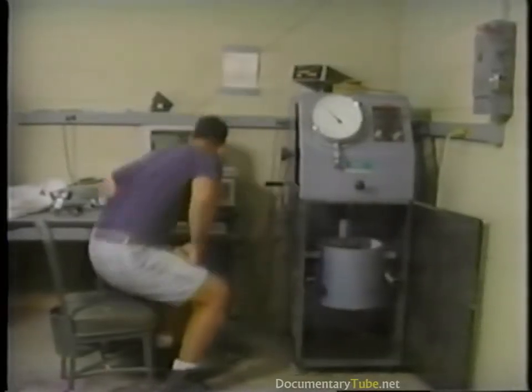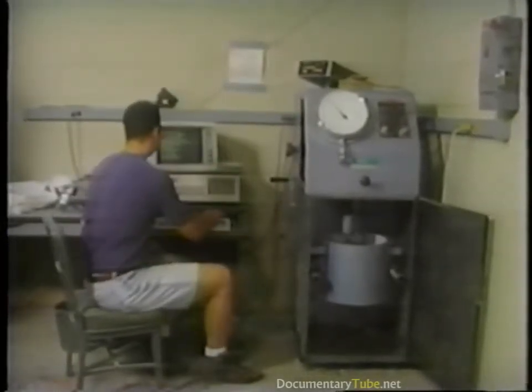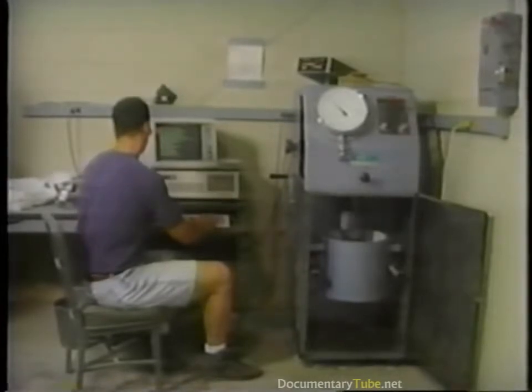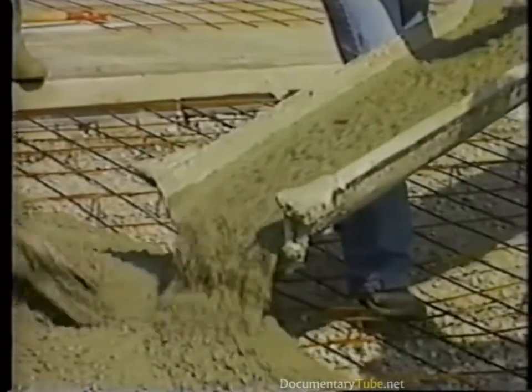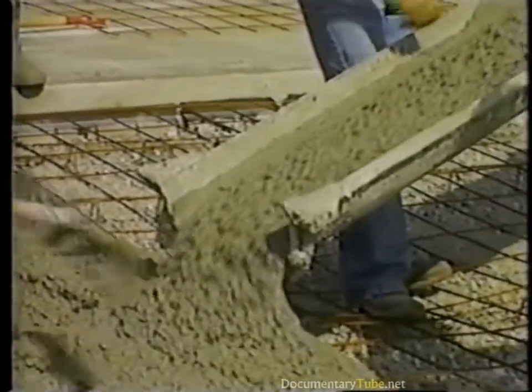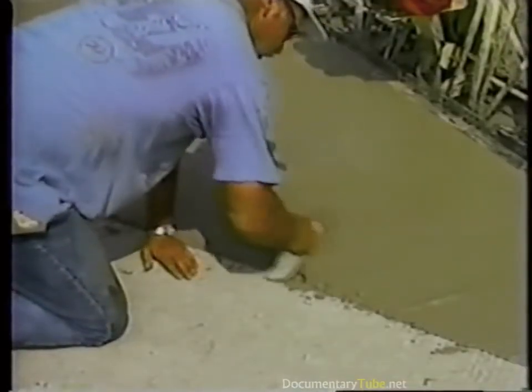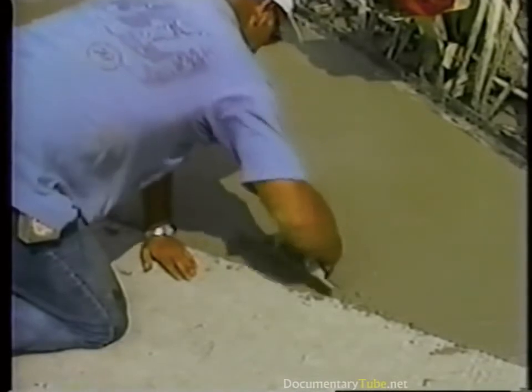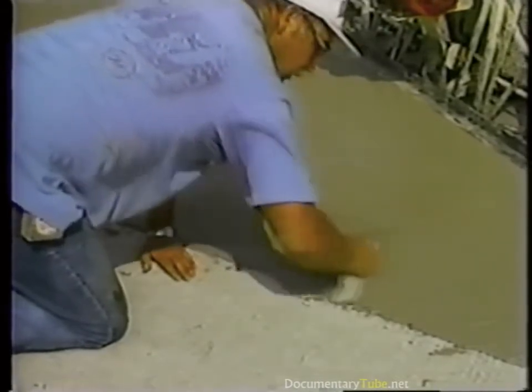At the time of setting, the yield stress starts to increase abruptly, and the ability to flow is lost. Researchers are interested in flow characteristics to understand how the process of hydration stiffens the fresh concrete and leads to set in the concrete.